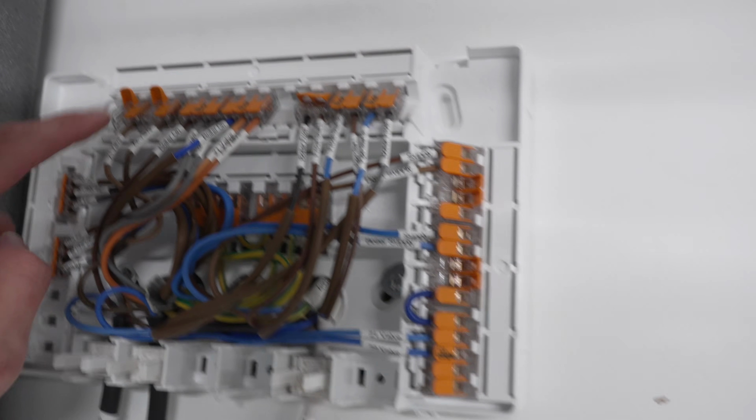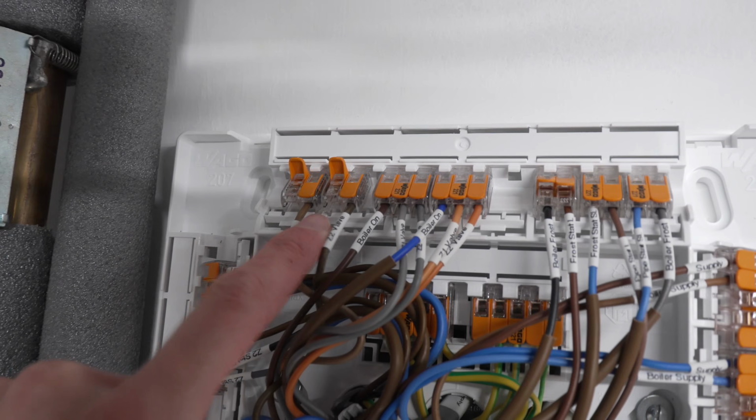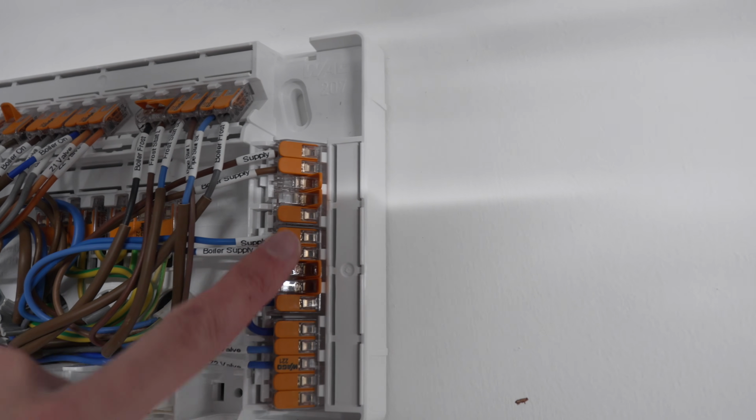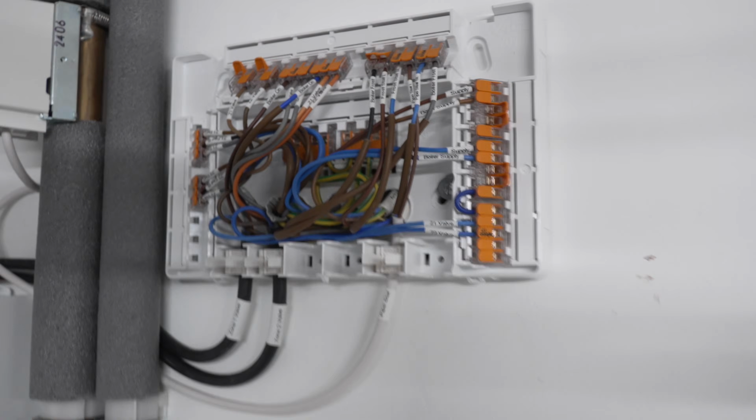So now all we have is the terminals that go off each zone valve empty, ready to connect the new Wiser hub to, and then likewise we have neutral and line over here that we can also connect to the Wiser hub. So now we just need a cable from this into the Wiser hub. Now, of course what you could do is just mount the Wiser hub right next to this, bring a cable out of this on the surface into it, that would be completely fine. But this is quite high up, you can see it's right against the ceiling. And being in the garage, I don't really want cables trailing down this wall here because it'll get bashed.